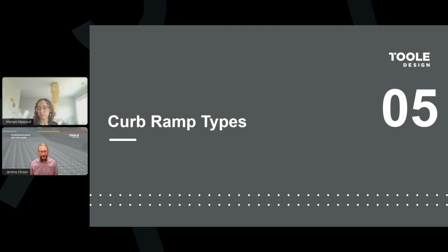You can alter the slope of your ramp and lower it, or you can alter the slope of your gutter, or you can change both of them. But the longitudinal slope along your curb line is not going to fundamentally change or would not change much. And so you would not be trapping water by creating a localized low point or anything like that.